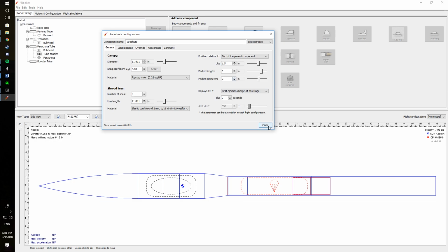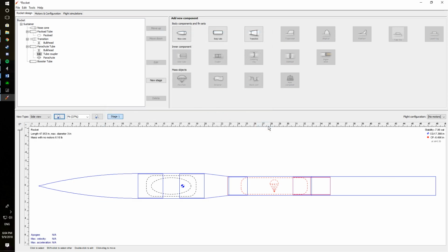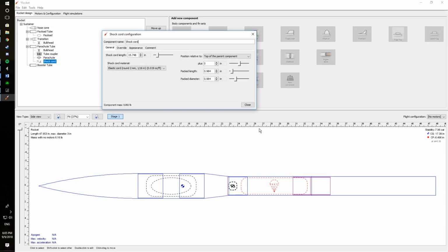You might notice that to add things in OpenRocket to the rocket, you click the button that is their title, and that is the majority of the work. Yeah, it's a very simple program, especially once you know what you're doing. You can build a rocket quite quickly. Last thing we'll be adding to this rocket to make it fairly universally functional is a shock cord, which just simply attaches the parachute to the rest of the rocket. In this case, via the bulkhead, it will be just a 1/2 inch off. You can really make the volume whatever you want. It's up to recovery to determine these sizes.